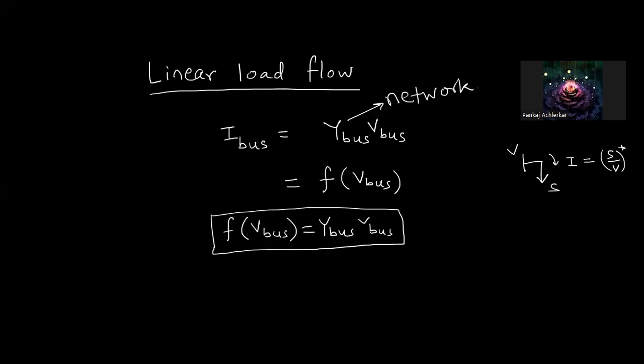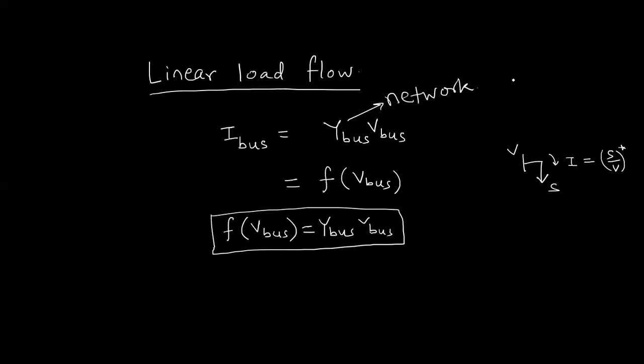Suppose we are running state estimation or optimal power flow, which is required for real-time operation, and our scheduling interval is, say, 5 minutes or 15 minutes. In that short duration, if we ask the algorithm for a very accurate solution, it will take a lot of time. It may not converge within 5 minutes for a practical system with a large number of buses.